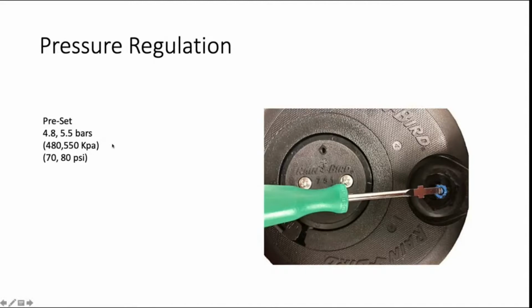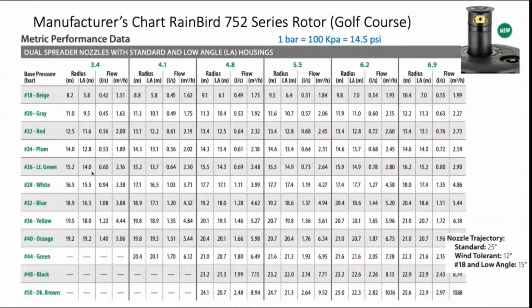It will not increase pressure. You're only knocking it down if you have excess pressure. And that can be good to prevent too much sprinkler breakup of the stream and creating very small droplet sizes. Very small droplet sizes creates drift and goes off target, and it's subject to more evaporation. So you can only reduce pressure with pressure regulation from the supplied pressure. You can't increase it above the supplied pressure, which we think was obvious, but some people probably don't understand that.